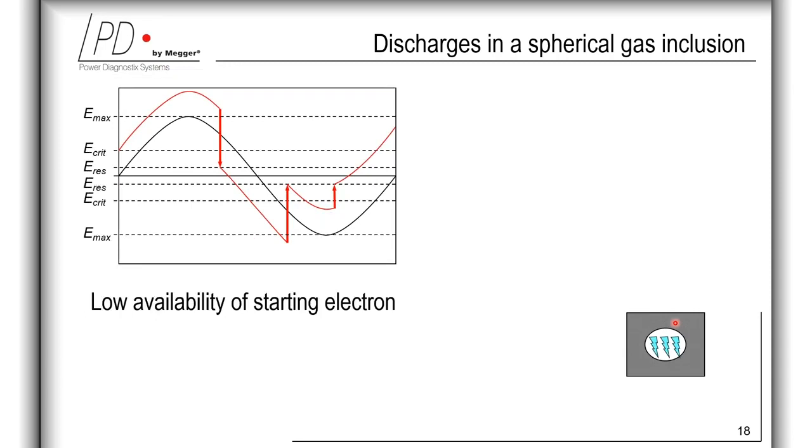In case there is no such external irradiation, then only ionization processes of the natural radioactivity, as well as the described so-called detrapping mechanism, would provide the free electrons needed to start the electron avalanche of the partial discharge event.